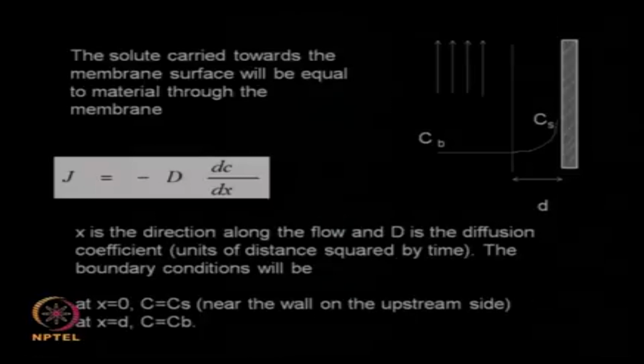It depends on the liquid properties like viscosity, the density and the surface tension, and then it depends on the flow of the liquid near the wall. If the flow is turbulent, we are going to have a smaller diffusion distance or boundary layer. If the flow is very low, we are going to have a very large boundary layer or diffusion thickness.